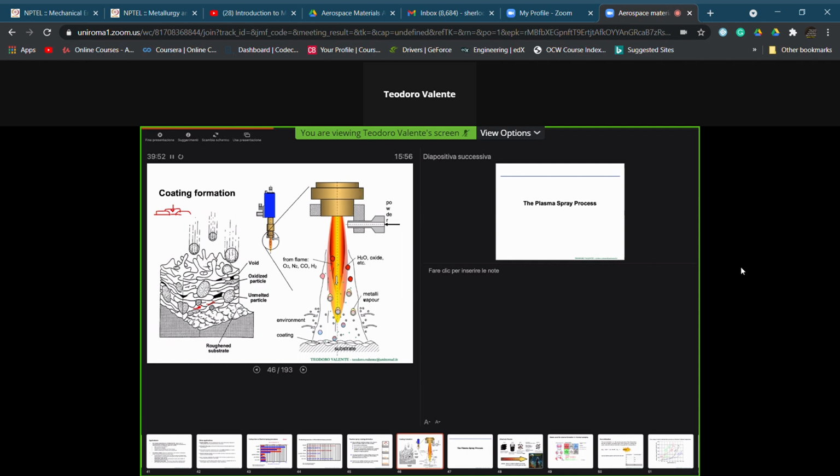One of the two most common defects which can be found in these processes, obviously with different importance depending on whether we discuss HVOF or plasma, is this: if we have a granulometry distribution of the powders, we can expect the optimal results for the average size, while the powders which are higher in average diameter are not completely melted, but can still be found inside the fabricated coatings, because they can be entrapped by the smaller powders which were melted and then solidified.